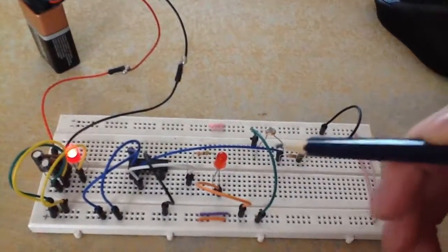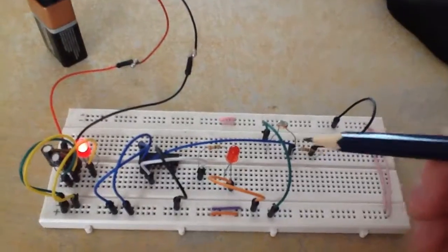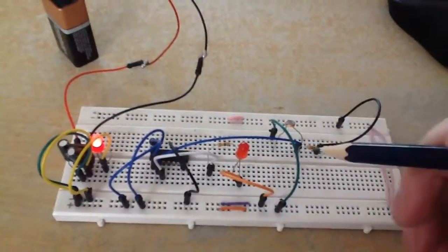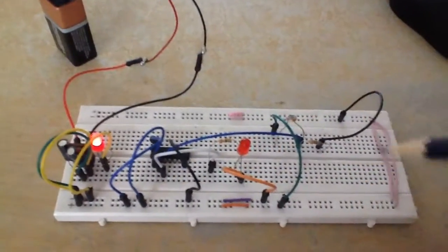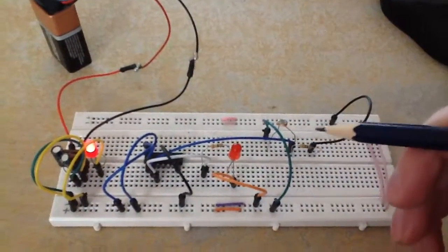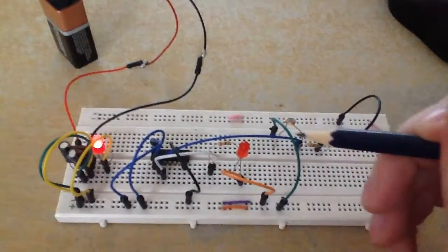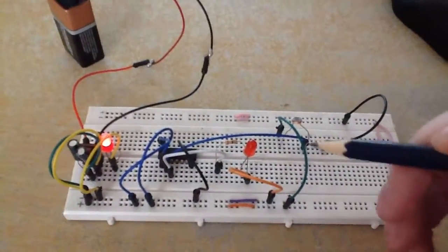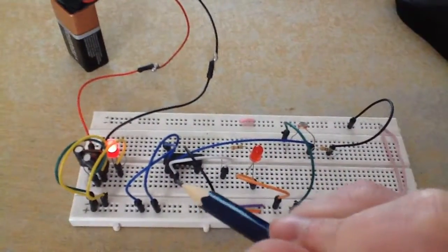We want to get around 0.8 volts or less here, because if you look at the spec sheet, it will tell you that to ensure there's a low on pin 2, which we want, the voltage should be anywhere from 0 volts up to 0.8 volts. So we do get 0.8 volts here, which means that pin 2 is low.